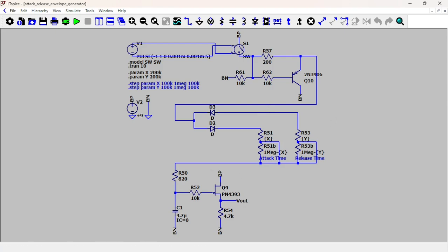Okay, what's the purpose of this guy here? This is a JFET. I think you could have used a MOSFET here, but he's using a JFET, fine. So this is the gate, this is the drain, and this is the source. And in this configuration, it's a common drain amplifier, aka a source follower. So its only purpose is to buffer here.